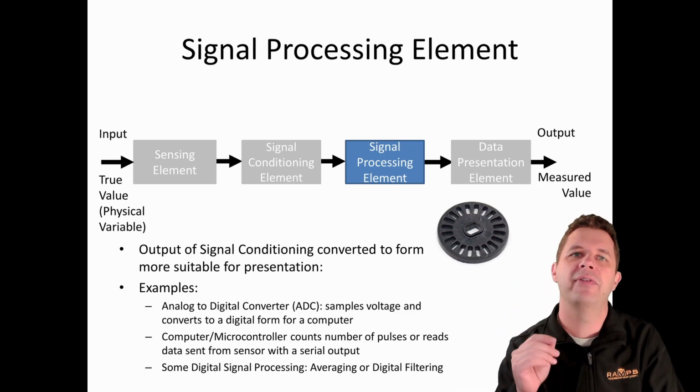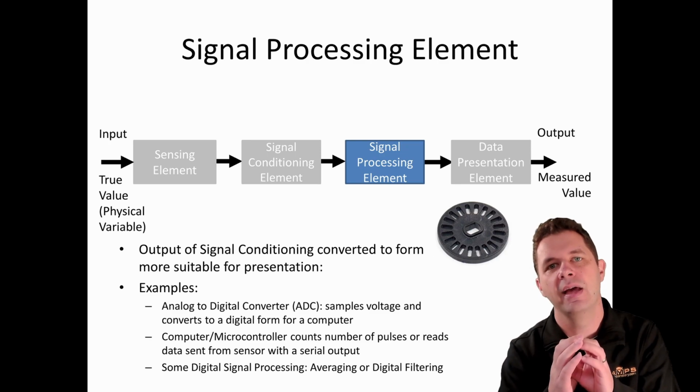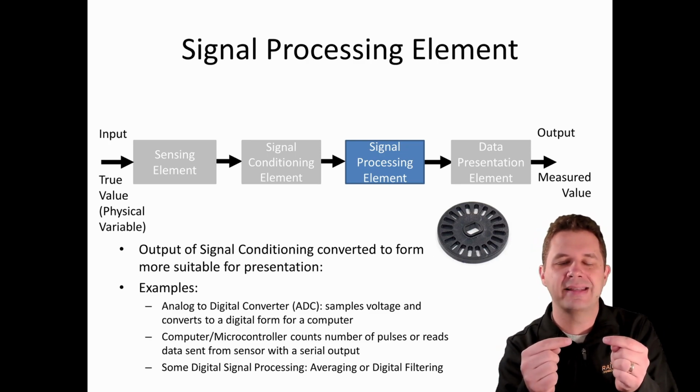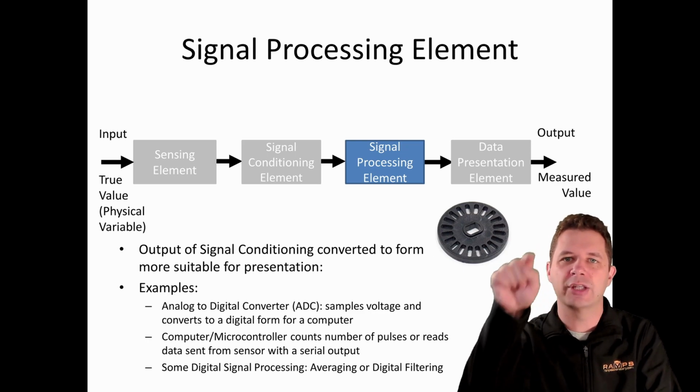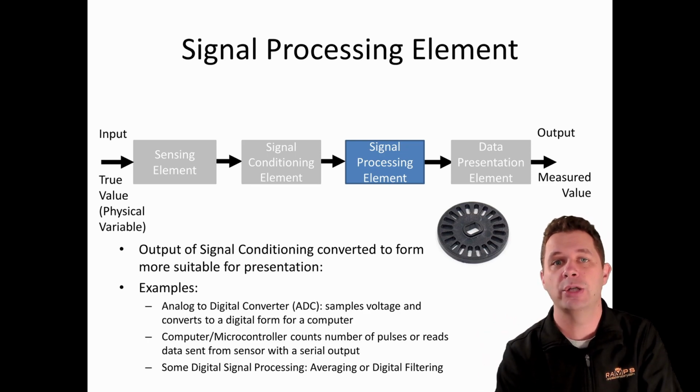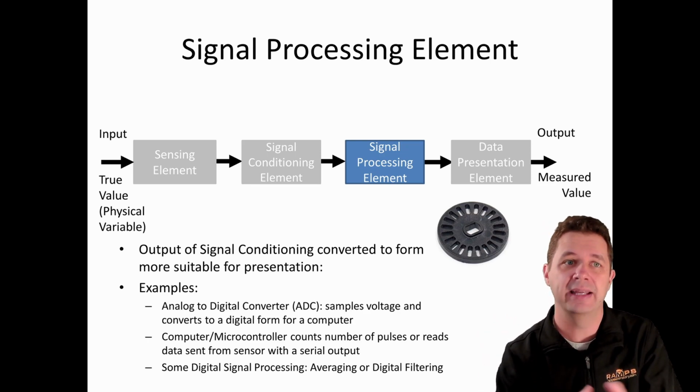And you see above here, we've got a little rotating disc. We often have a little light source across that disc. And as that disc rotates, the light source is interrupted and not interrupted. And we'll have a little waveform that's like a square wave. That can allow us to measure, for example, how quickly a wheel's rotating.